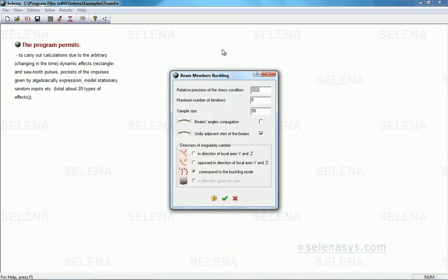The reason for the premature loss of stability of core elements is the presence of small initial imperfections in them, in other words, curvature. Due to this, even with the central compression of such rods, a moment stress state arises in them. And if the total stress in one of the core fibers from the longitudinal compression and from bending reaches the limit value, then the rod after this cannot bear the load. This regime just provides the calculation with slightly curved rods, in accordance with the selected norms.